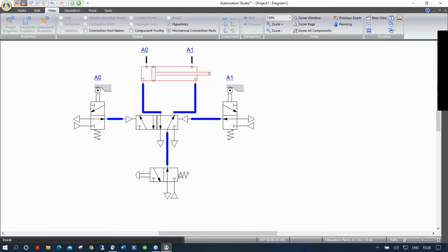This is important because, for example, if you have a solenoid valve that is controlled with an electrical circuit, okay? If you have a checkbox here like that, and you have a solenoid here, and you trigger that solenoid, even though it's well connected, it will not move because it's forced in that position, okay? So keep that in mind because I've received many requests down the road. Before, we used to have very small triangles, and people weren't seeing it. Now with the big check, you see it. But sometimes they send me a circuit and say, well, how come it doesn't work? It's simply because some of the valves on the circuit have been locked in place, okay? So keep that in mind.